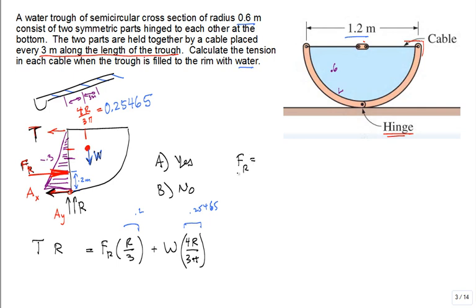So now I say, great, give me F of R. What is the resultant from the distributed load, hydrostatic, triangular shaped on that side? Is it going to be an average pressure, or the pressure at the centroid times the area? Is that the way we calculate it?